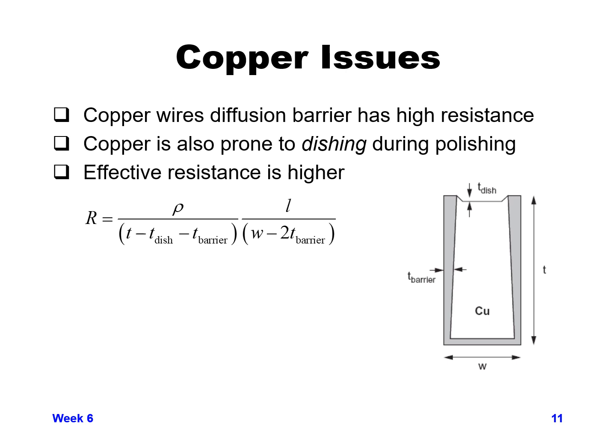And so your effective resistance of your copper wire isn't just based on the total width of the metal wire, because the width of the copper is reduced from the total width of the wire by this additional barrier. So the effective resistance is going to increase because your effective width of the copper is less than the total width of the wire. And so you do get an increase to your copper wire resistivity because of that.